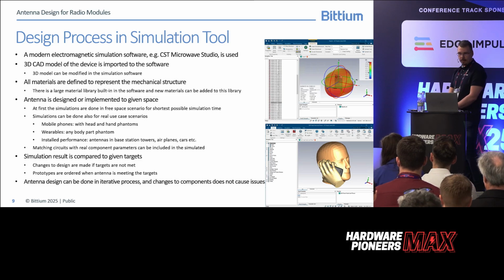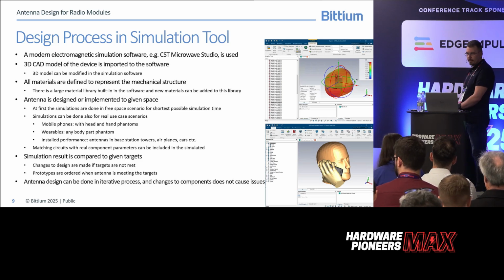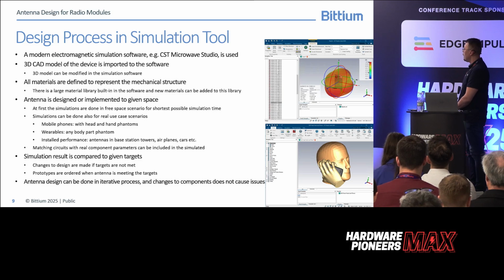Then the antenna is designed or implemented in the given space. By implementing, I mean that if you are using off-the-shelf antennas, like FPC antennas or chip antennas, we take the mechanical and electrical model of this antenna and then implement it in the device.